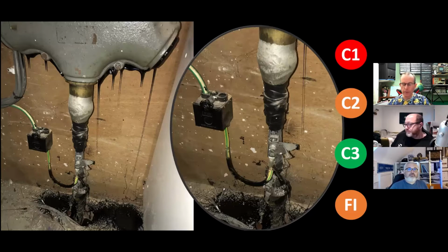PME, yeah. This thing about the PME, it's on the electric vehicle charging course. It's actually in that if you get a TNS, you're supposed to assume it's going to be PME regardless of whatever else, unless you can get written confirmation from the DNO that it is TNS and will stay that way. But of course, that's never ever going to happen in any kind of situation.